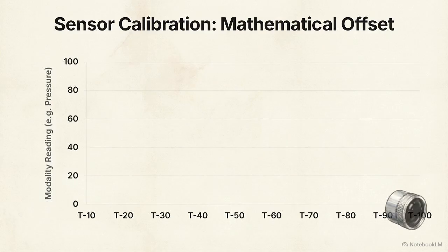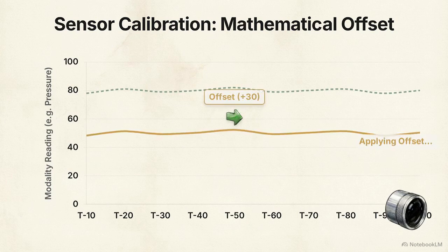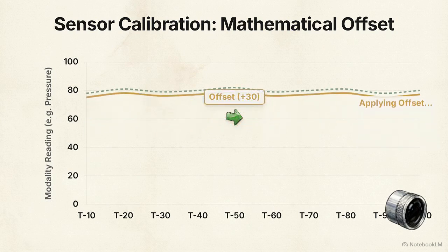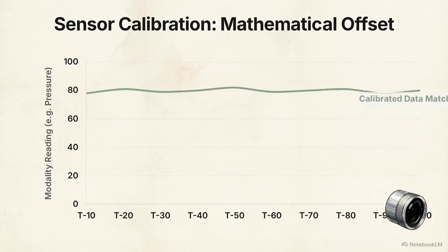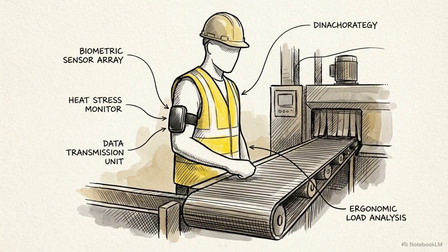This chart shows how that inaccuracy is corrected. Engineers must conduct explicit laboratory and field evaluations to determine the error margin, then apply a mathematical offset to shift the factory baseline up to the true measurement. This rigorous approach to physical capture is now extending beyond machinery. Layer 1 increasingly integrates biomedical and wearable sensors directly into factory operations to monitor worker safety.